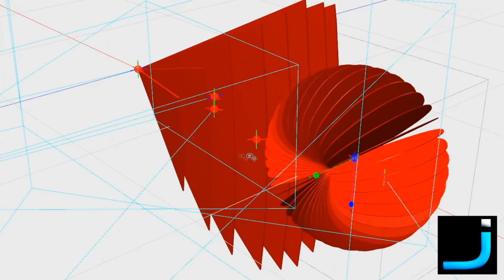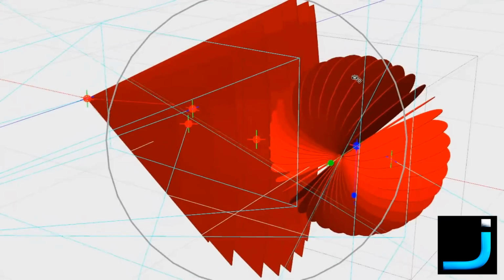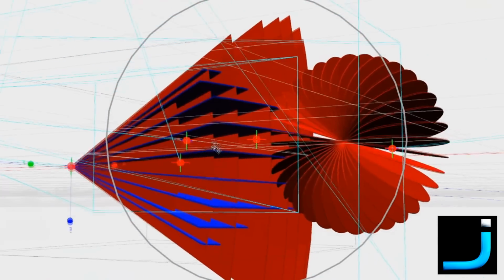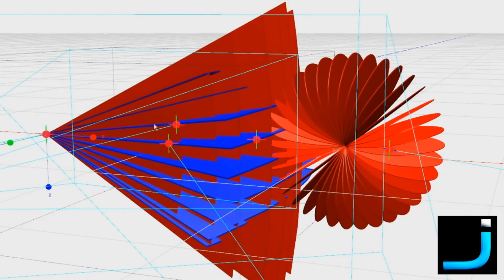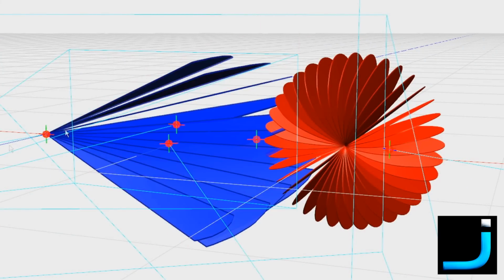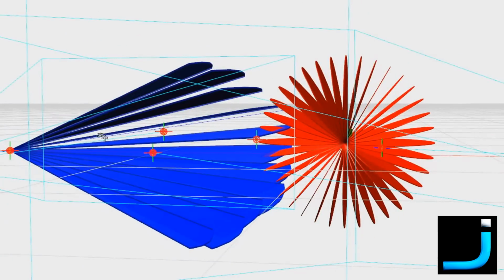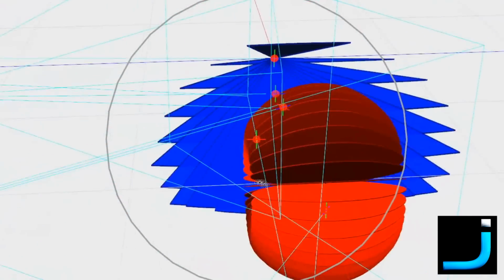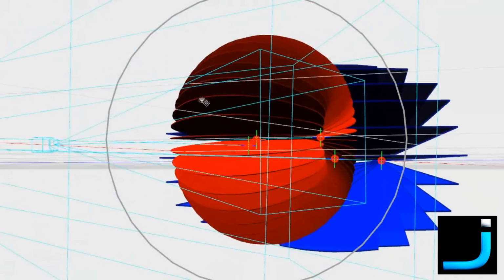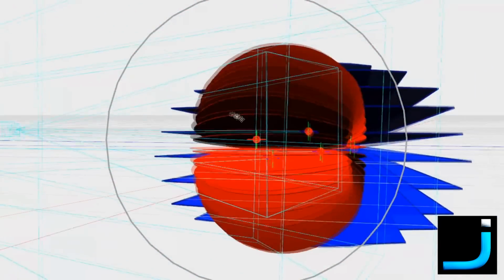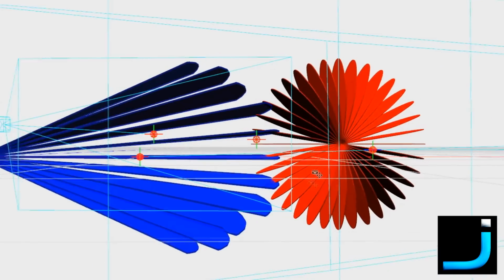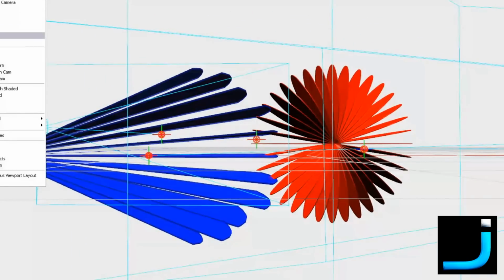the vertically polarized antenna built in, but there is also a horizontally polarized antenna. It's exactly the same as the vertical one, it's just mounted at 90 degrees. So we can turn off the vertical one, and so this is how it looks for that. Again, it's about a 50 degree field of view, but the antenna is mounted internally at 90 degrees, giving you horizontal polarization. So this is linear diversity. There's a diversity between the polarizations essentially.